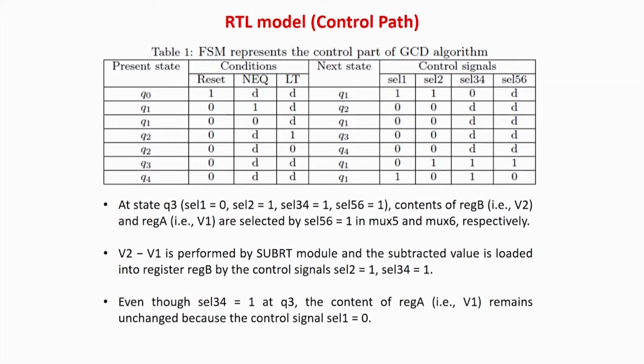So there will actually be 5 states, Q0 to Q4. Four states would mean a 2-bit machine with 2 flip flops, but 5 states means the number of flip flops required to implement the circuit will be 3. Now again, the important part is that this is very standard digital design. You can easily go back to your higher BTech level digital design, and you can easily find out how a state machine can be implemented.